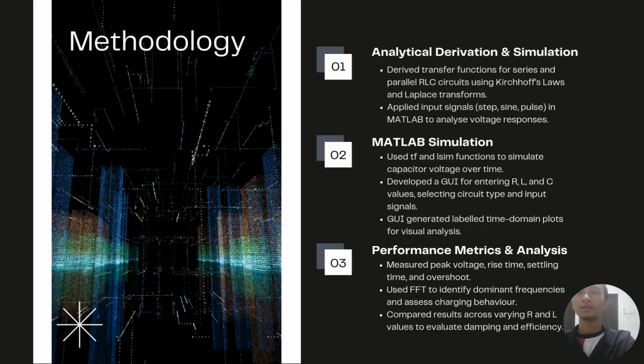For our methodology, we started by deriving transfer functions for both RLC circuits using Laplace transforms. Then, we simulated capacitor voltage in MATLAB using TF and LSIM with a custom GUI to input R, L, and C values. Finally, we analyzed rise time, overshoot, and frequency content using FFT to evaluate how R and L affect